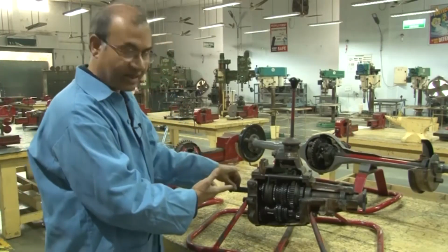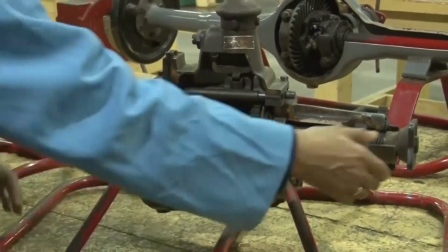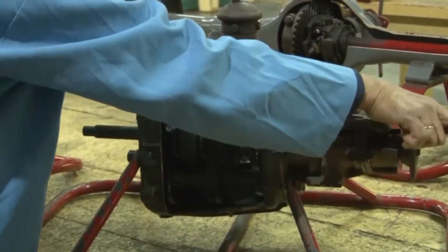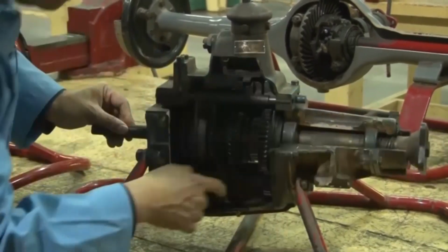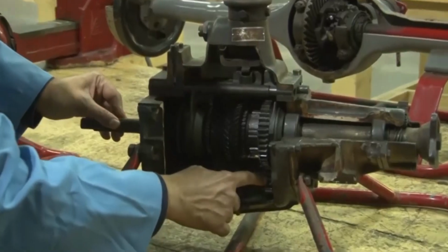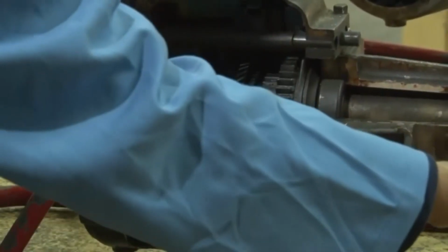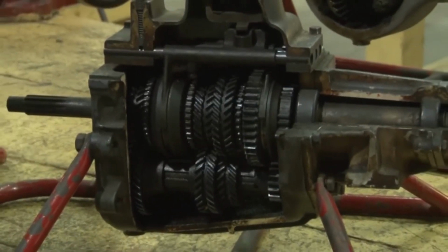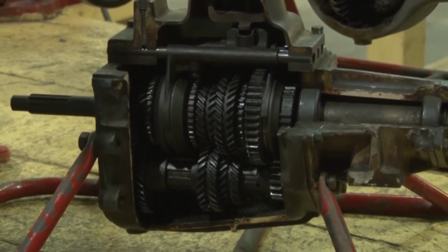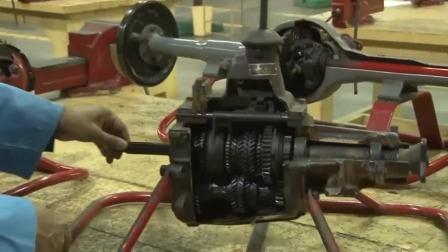Now, if you change the gear, for example, you have changed here. If you rotate this, this will rotate, and as you can see, the transmission is going from the bigger gear to the smaller gear. Bigger gear means more number of teeth, to the less number of teeth. Therefore, the speed of the output shaft here is higher, as you can see. So, there are first gear, second gear, third gear, up to 5th gear, and there is a back gear as well. Mr. Aman is going to demonstrate how those gears are changed.